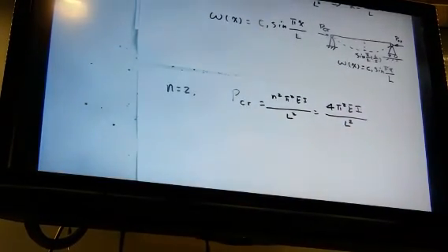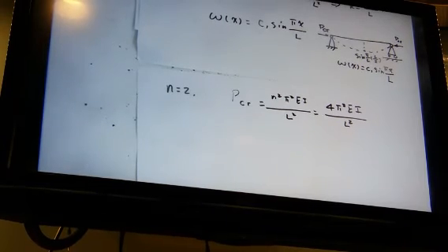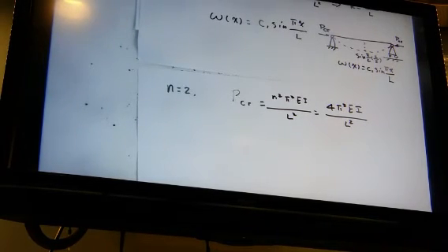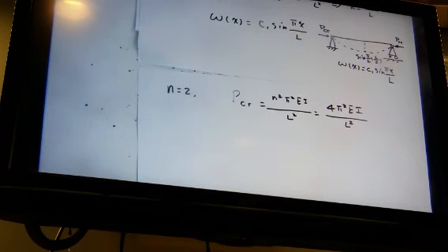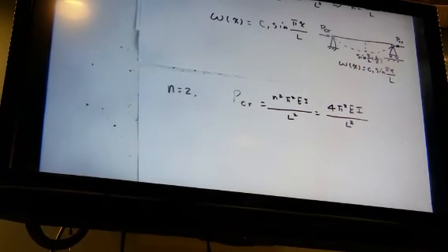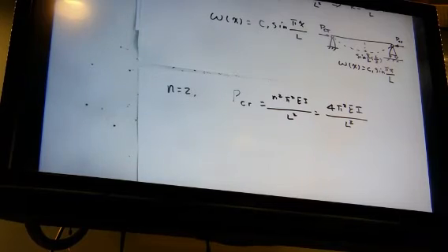This is the critical loading for the second buckling mode occurrence. Keep increasing the loading a little bit after the first buckling loading does not give you the second mode buckling. You have to approach another critical loading to have the second buckling mode.